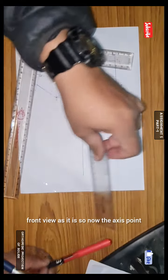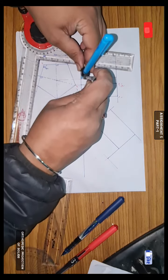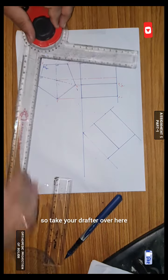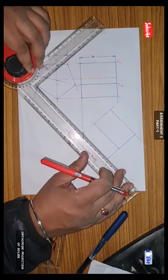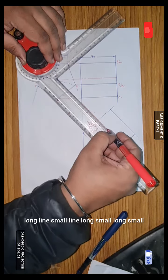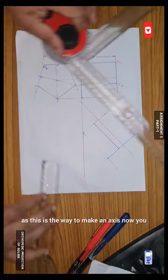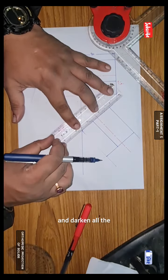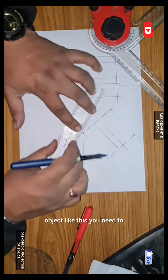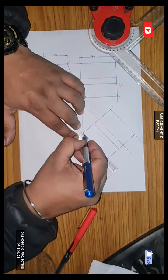So now the axis point, you need to mark the axis also. This is your axis. So take your drafter over here and make an axis like this: long line, small line, long, small, as this is the way to make an axis. Now you take a small scale and darken all the boundary of this object like this. You need to make the boundary.